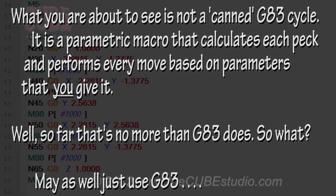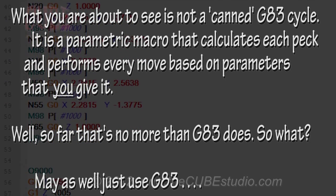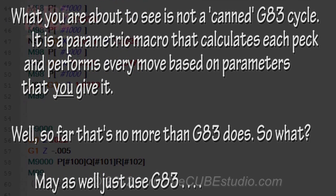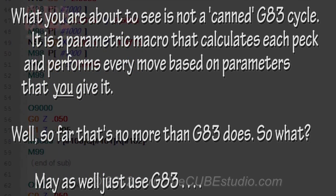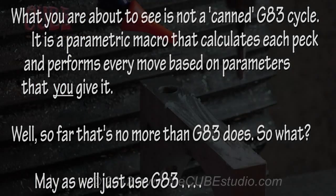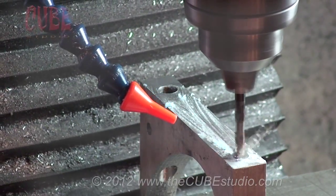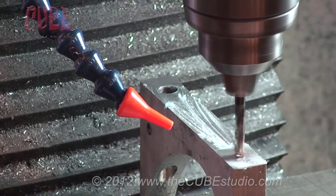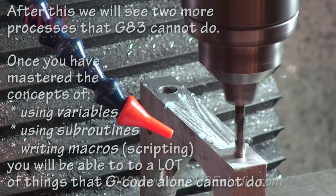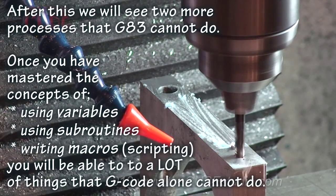What you're about to see is not a canned G83 cycle. It's a parametric macro that calculates each peck and performs every move based on parameters that you give it. Well, so far that's no more than G83 does, so what? May as well just use G83. After this, we'll see two more processes that G83 cannot do.